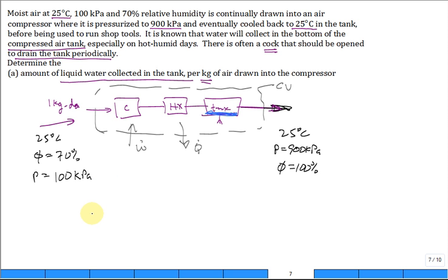analysis of this, you'll say, what is the omega coming in? What is omega? It's how many kilograms of vapor per kilogram of dry air. Well, it's 0.622 PV divided by P dry air, true? So a little bit of work. What is PV?